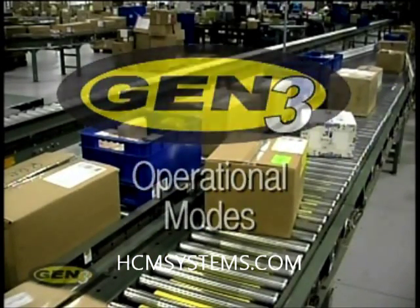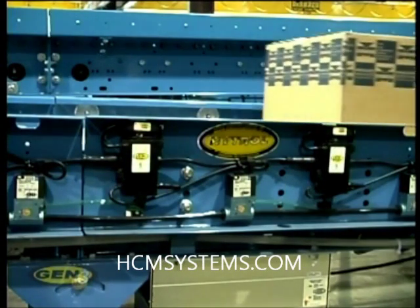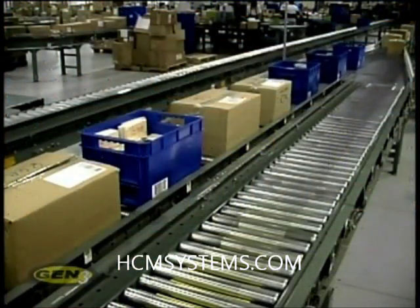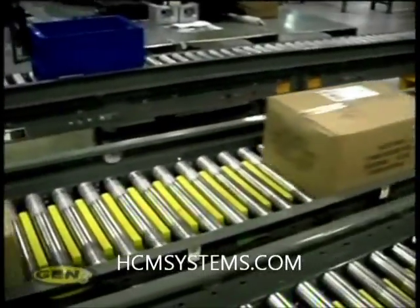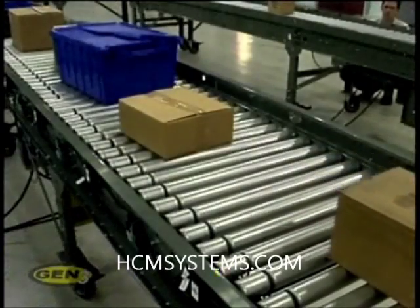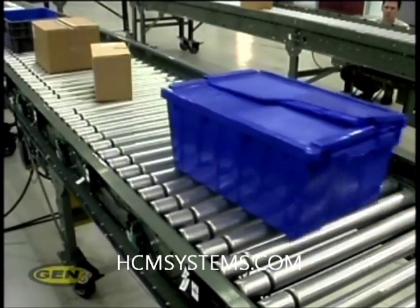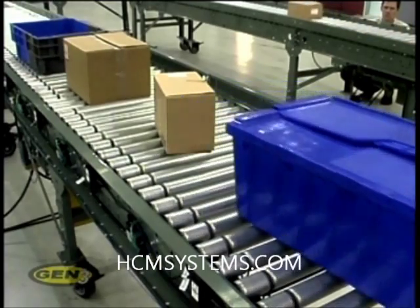Operational modes. The EZLogic system provides two primary modes of operation for transporting and accumulating product: singulation mode and slug mode. Singulation mode provides individual carton control during transport and accumulation. Each carton is assigned a zone as it accumulates on the conveyor. When released, the cartons are held in their respective zones until the zone immediately downstream is clear. The cartons are thus separated or singulated as they are released and/or transported.